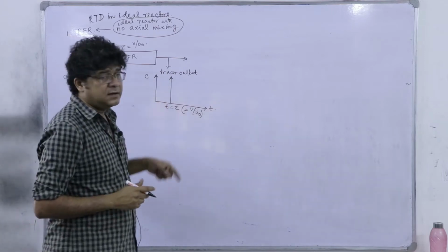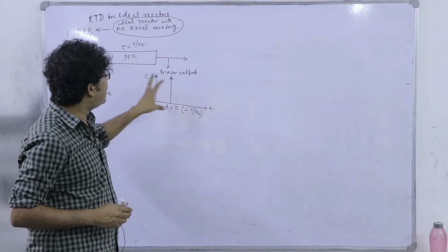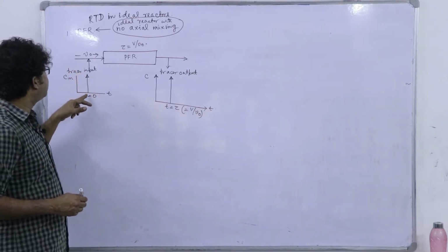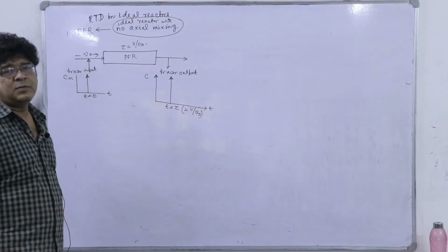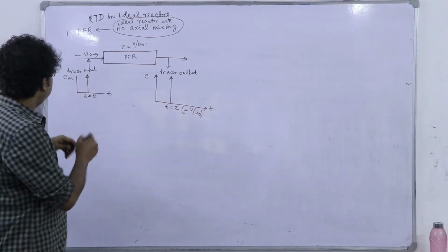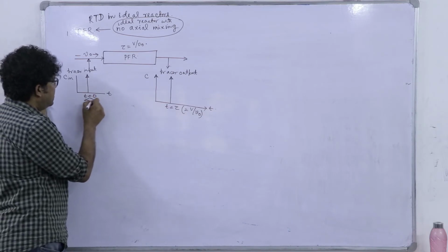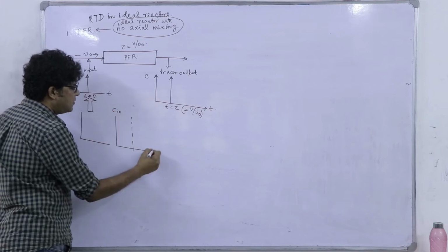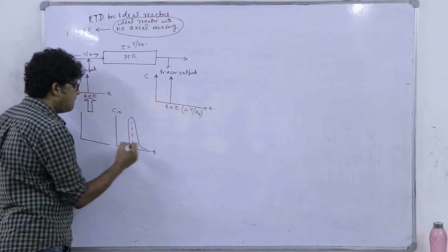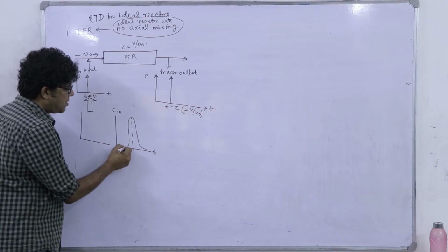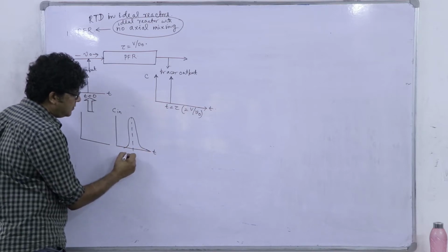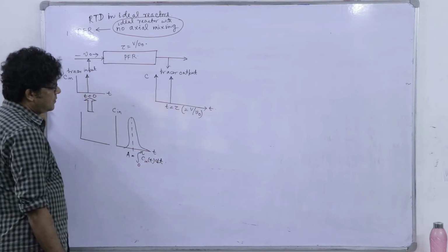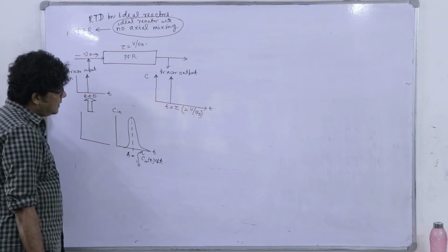Now, this is not the typical unit impulse, because the area under the curve is not exactly equal to 1. Why? Because the spike we have given is infinity multiplied by some infinitesimal amount of time. Actually, it is an idealization of a typical pulse input, and there are two steps of idealization. Actually this C_in versus t is like this, and there is a certain area under the curve, and this area A is the integral from 0 to infinity of C_in(t) dt.